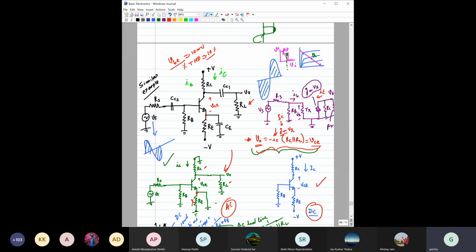Okay, because we have approximated. I agree with you. If we increase this V of BE, the total harmonic distortion will also increase, and we will lose some linearity. But the criteria we imposed is this 10 millivolt V of BE. Now please correlate this V of BE restriction to IC. Please let me know in the next class: if you change V of BE around 10 millivolt, what is the maximum change that is possible across IC?